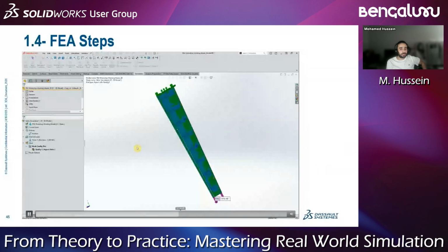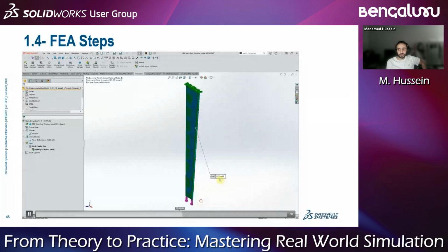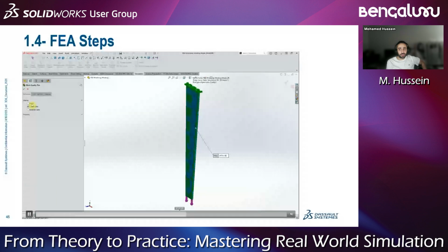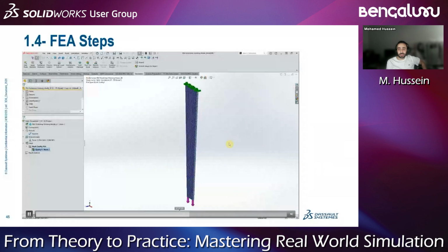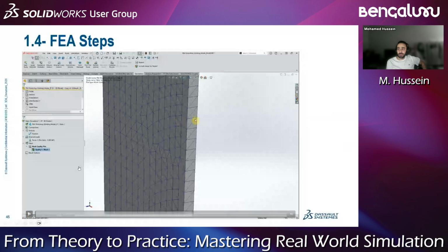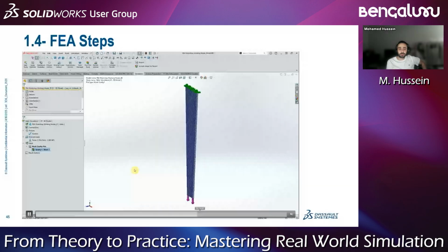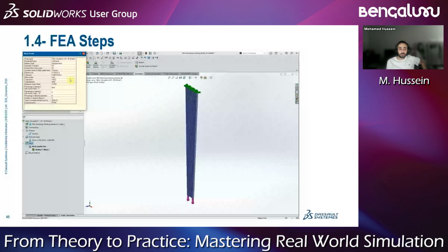What I will do right now is generate a finer mesh and check what happens. This is the mesh appearance right now. I still have only one element through this. If you check, first of all, I have 8,000 elements. Previously, I had only 1,500. How many elements have an aspect ratio less than 3? Almost all of them. But check the time used to complete: 2 seconds.